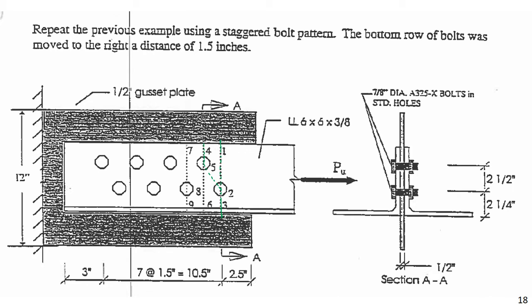It also couldn't do that because it would have to cross through additional bolt holes. We couldn't tear off just here because these bolts would still be connected. So I suppose we could postulate something like, what if it did something really weird, like came down, then took a right turn, or from its perspective, a left turn. It comes down, goes this way, then goes diagonal, then goes across, then comes down. But that's not going to happen, because everywhere your failure path touches, you're requiring that steel is being torn. And so, generally, the shortest path is going to be the critical one.